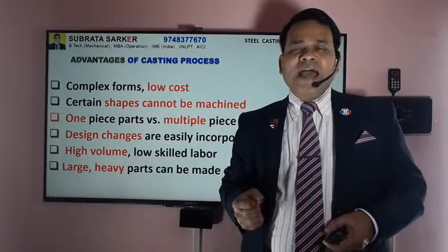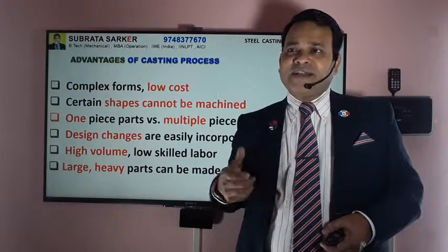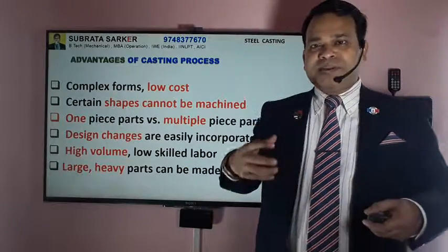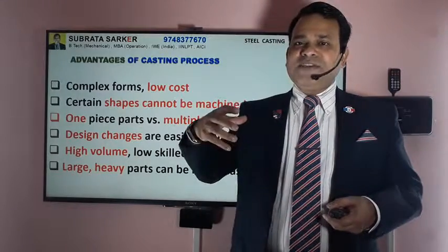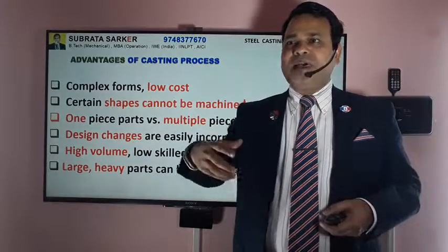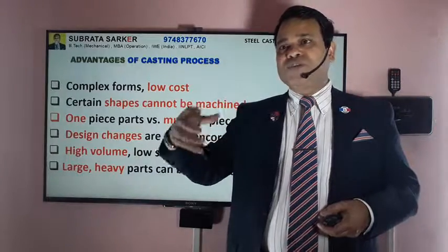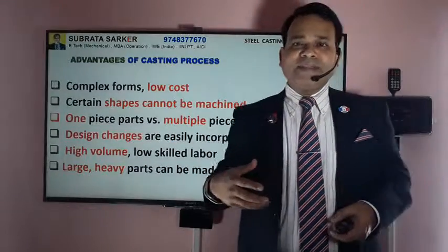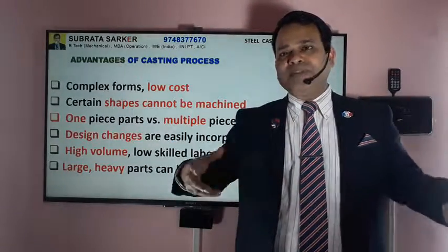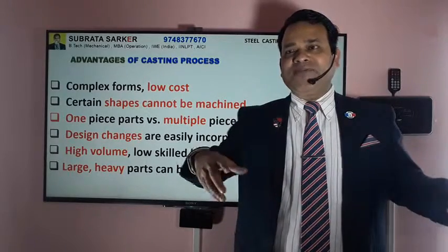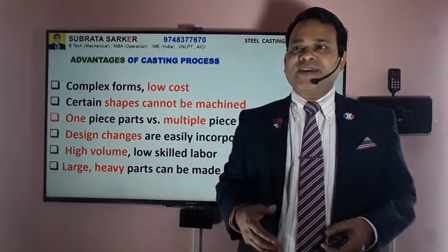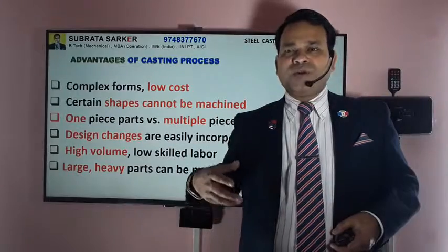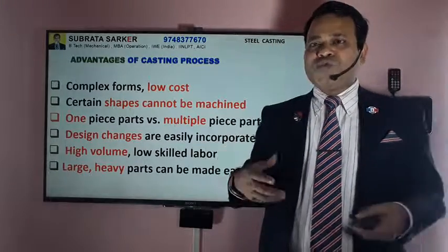And there are obviously some drawbacks in the casting process. In casting, you are creating the material from molten metal by solidifying it. So if something goes wrong in the process, there may be internal defects or porosity in the material, and the material gets rejected after so much processing. In some cases distortion or shrinkage happens in the casting, so you don't get the final required geometry and the job may be rejected. In some cases impurities are trapped inside the casting, and you find that by UT or some testing process, but by then the process is over.